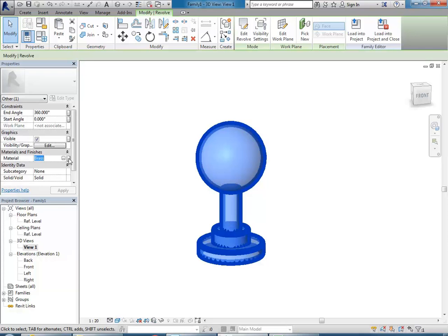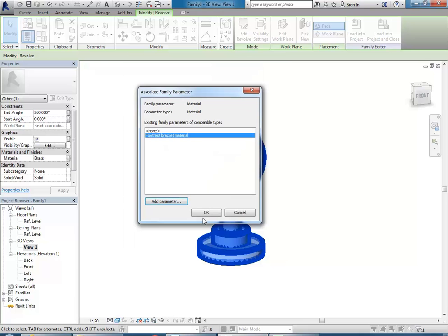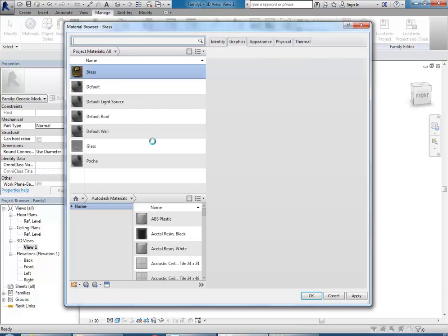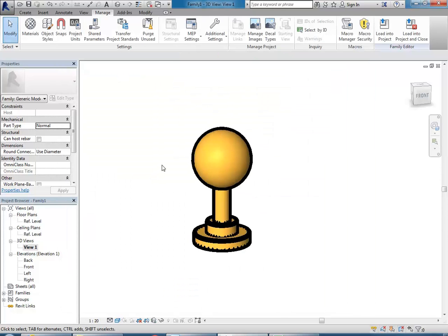So hopefully you're getting used to that, so you just click on this button here, and it takes a couple of clicks, and so we'll call it footrest bracket material. Don't know why my colour isn't coming up there. Let's have a look. Oh, yeah, because it's not in the material. There it is. Done.